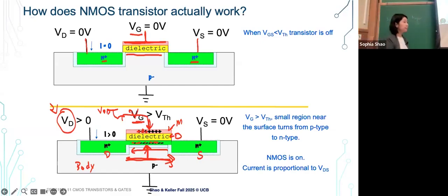Sorry, the light green is just electrons as well. Oh, the light greens are actually doped here. So for N plus, you can think of it as starting with the base transistor, and we dope a lot more electrons into it. Oh, you mean this green? Yeah. Those are just electrons. Those are channels being formed there. Those are not doped. Those are electrons attracted to the channel, to the top of the body.